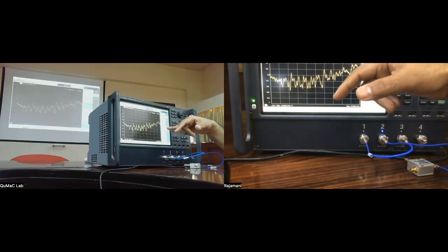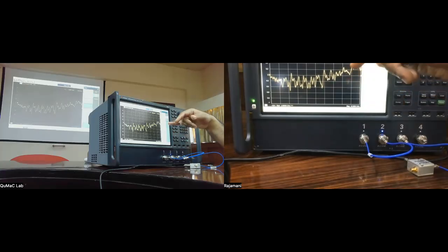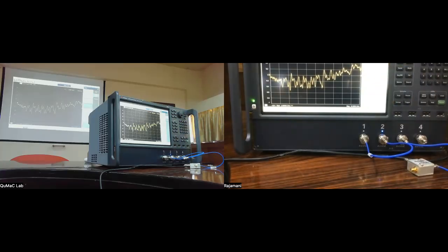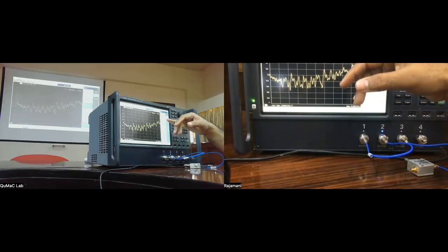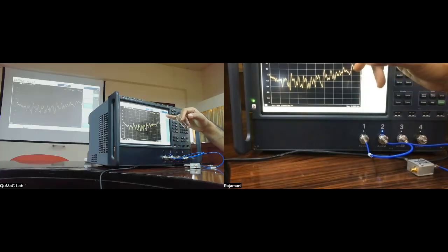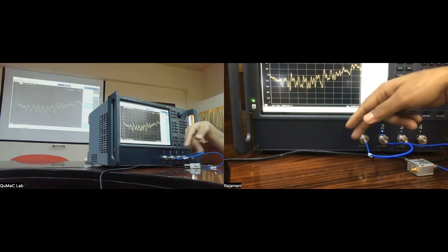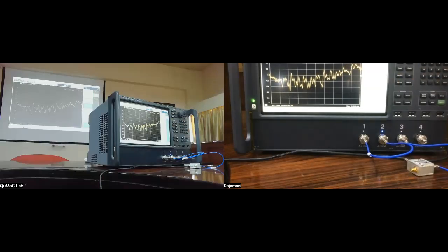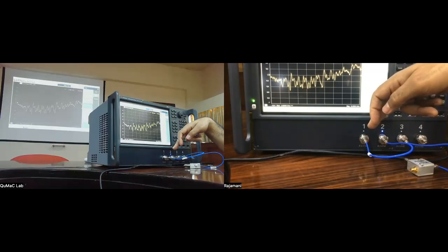It's actually saying a velocity factor of 1, which means I think it's assuming that it's traveling at the speed of light, so the distance here will correspond to 1.59 nanoseconds times the speed of light in vacuum. But this actual length is not correct: this is about 500 millimeters, which is 50 centimeters, and this is 12 inches.